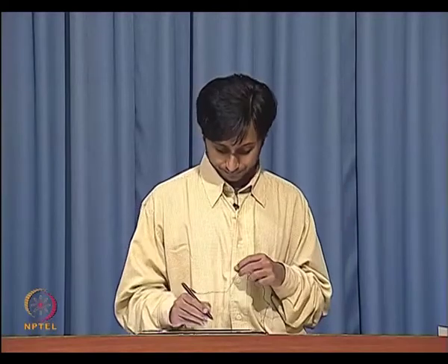Okay. The third harmonic and second harmonic are not really that important to us, we are going to filter them out anyway. What is more important are the intermodulation products. What you will realize if you do the mathematics is that the third order intermodulation products 2f1 minus f2, 2f2 minus f1 also follow the same curve as 3 dB per dB.